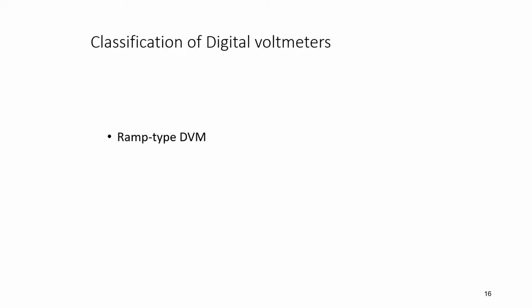The digital voltmeter displays AC and DC voltages as discrete numbers rather than as a pointer on a continuous scale as in an analog voltmeter. A numerical readout is advantageous because it reduces human error, eliminates parallax error, increases the reading speed, and often provides output in digital form suitable for further processing and recording.